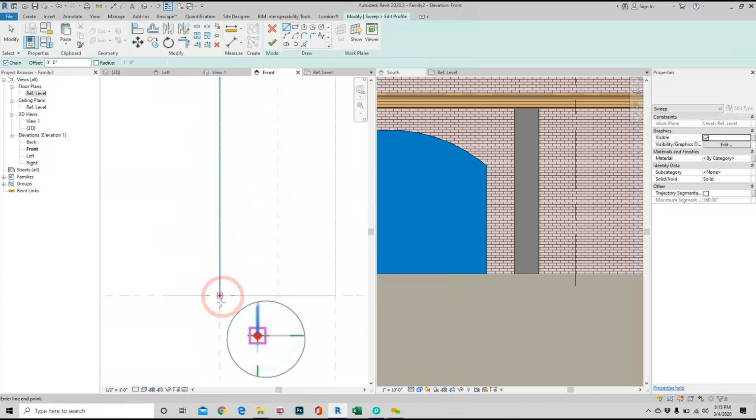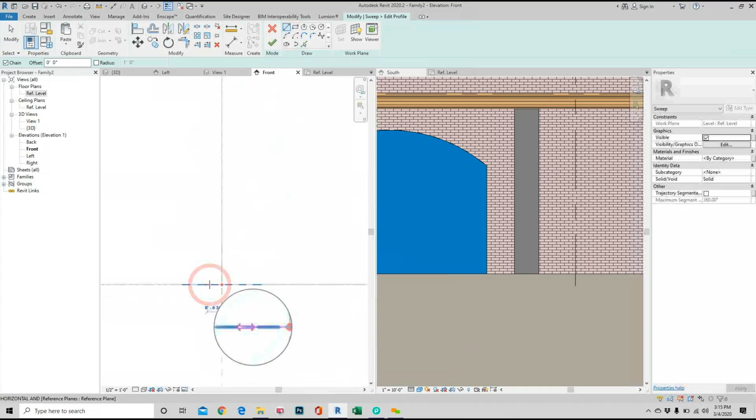So I can go and say, okay, on top of this, I'm going to come out. How thick is the wood? Now we start thinking on the wood. So finished wood, what's usually the thickness? Like a 1 by something. What would be the thickness? 3/4, exactly. So I would draw it at 3/4.